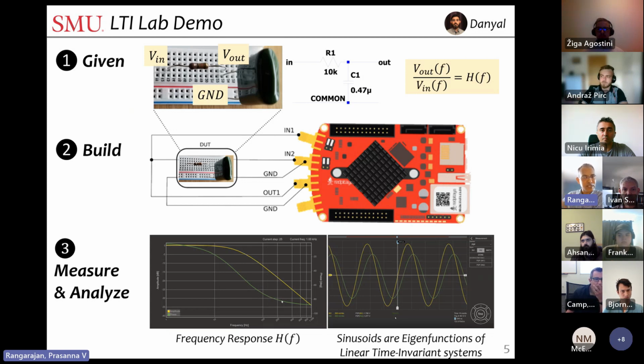So you could do something similar purely in discrete time, at which point we end up using the app, right? But the general idea would be to use the tools, in this case the spectrum analyzer of the scope, to try and understand exactly what the frequency response and the time domain response of the system would be to this linear system, which in this case happens to be a simple RC circuit, right?